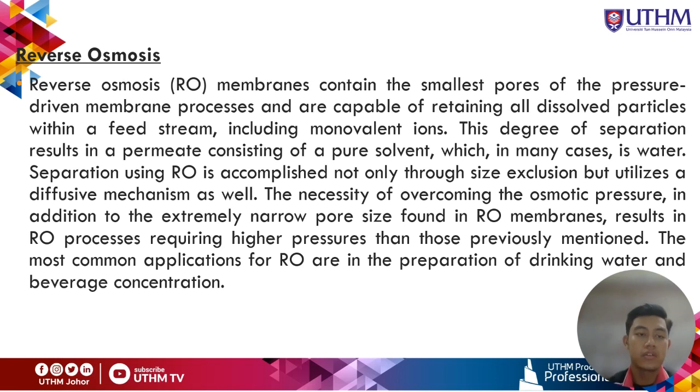Separation using reverse osmosis is accomplished not only through size exclusion, but utilizes a diffusive mechanism as well. The necessity of overcoming the osmotic pressure, in addition to the extremely narrow pore size found in reverse osmosis membranes, results in the reverse osmosis process requiring higher pressure than those previously mentioned. The most common applications for reverse osmosis are in the preparation of drinking water and beverage concentration.